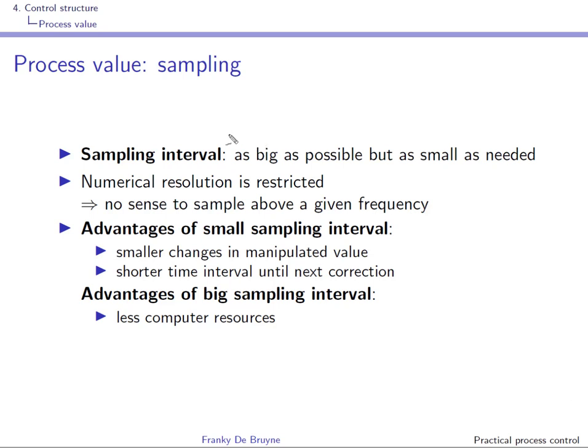Remember that the numerical resolution, this is the quantization step, is restricted. So it makes no sense to sample above a given frequency, because the actual difference between two successive measurements will be so small that you will not see it on the numerical quantized signal.